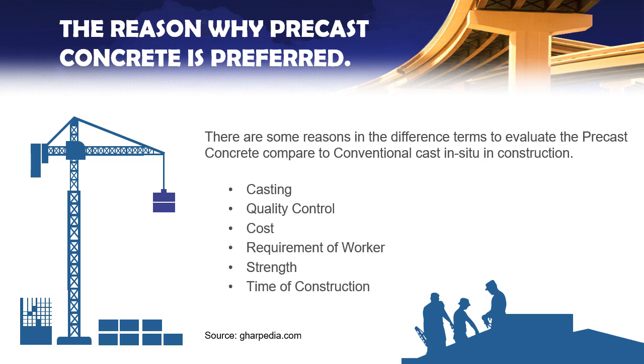Next, quality control can be maintained easily in precast concrete, while quality control and maintenance is difficult for conventional cast in situ. Next, in terms of cost, precast concrete is a cheaper form of construction if large constructions are to be constructed, while in situ concrete is a cheaper form of construction for small structures to be constructed.